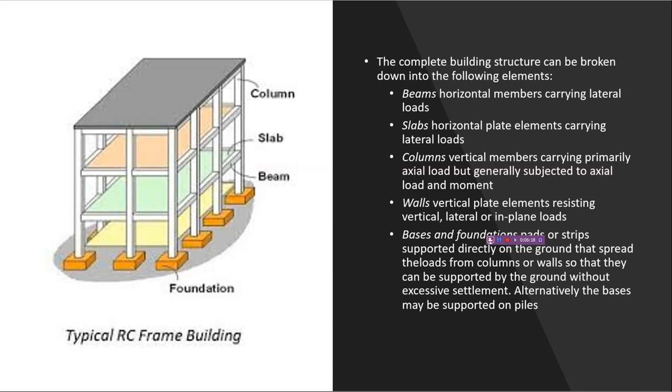So we will use normal things like columns and beams as a frame. Reinforced concrete walls are not rare, normally for tall buildings they are used. But for normal residential buildings of 3 to 4 stories, normally we opt to use framing instead of reinforced concrete walls.